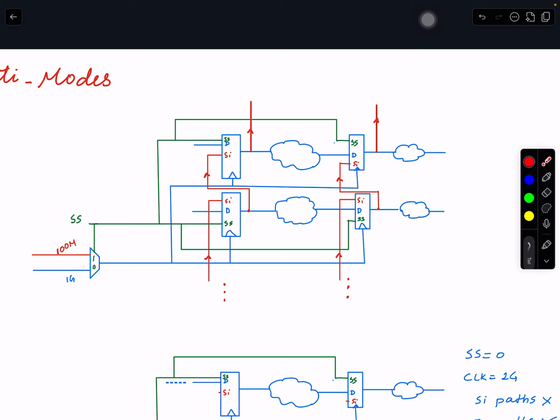So in terms of the topic that we discussed last week, where are you going to define your clocks? At which point? Here. You're going to define one clock here, 100 megahertz, and another one at 1 gigahertz. The clocks that you're going to define are generated clocks or create clocks? Those are create clocks at the source. This is the boundary of your block or your chip. So you're going to define create_clock 100 megahertz. You will give it -name, -period, and you will say at this port, and the other one at another port.